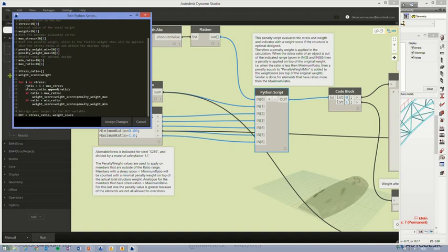Yeah, so I have for each. These are the reactions, of course. So I have to go to that. Is there a watch node? No, there's not a watch node. So these guys are the reaction forces for each of the nodes. So there are 1, 2, 3, and at the other side also 3. There are 6 supports, so I get 6 values. If I sum all these values, then I get the total weight of that structure.